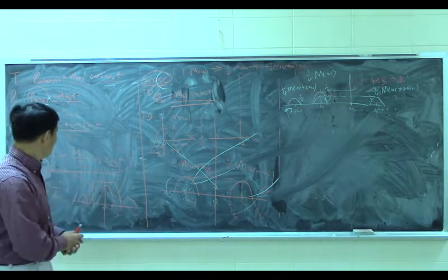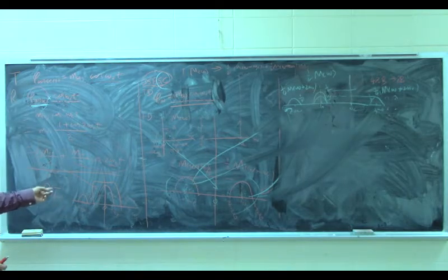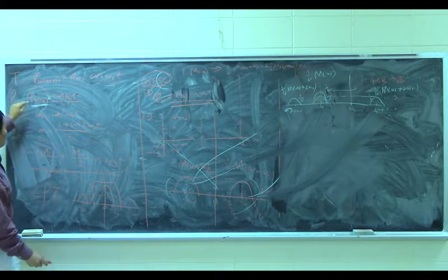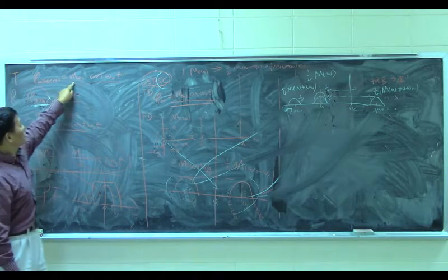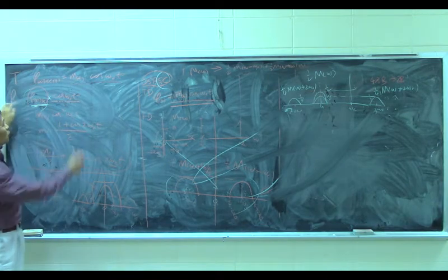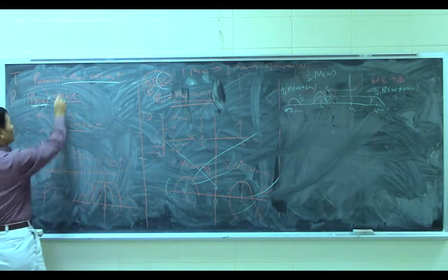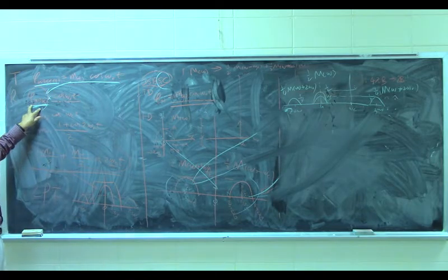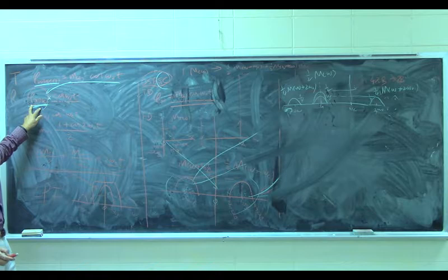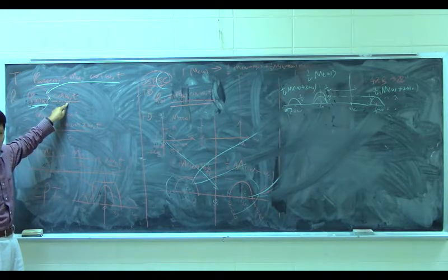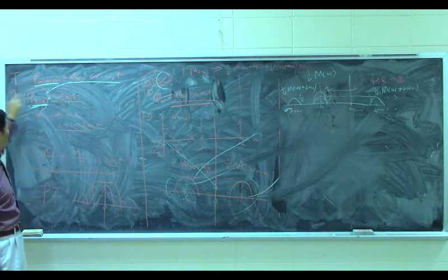Can you go over how to get the original signal from the transmitted signal again? Okay, at the transmitter you do this times this, right? That's modulation. And at the receiver you receive this one, right? So that is this part. I see it. It's actually the same thing. You need to do an extra step. You multiply by this cosine omega c again. This is what the receiver needs to do.